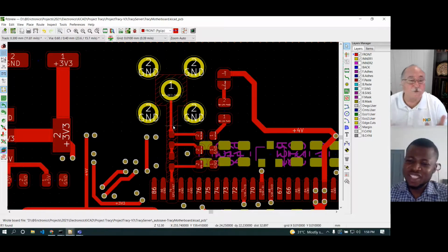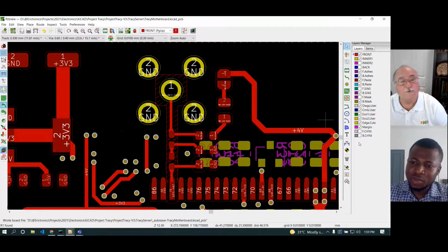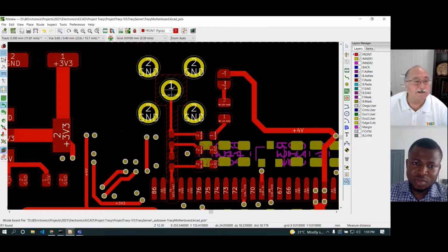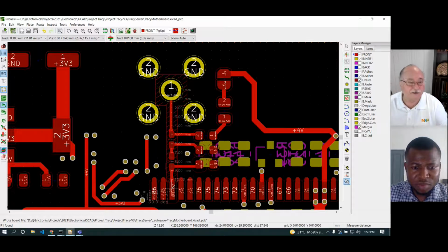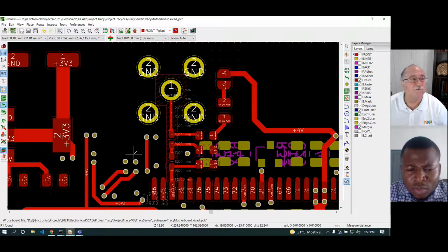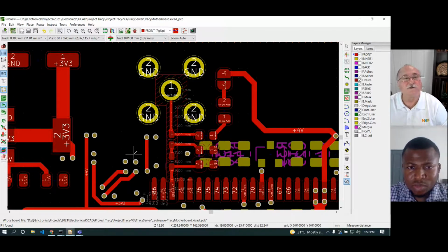So the important thing here is, in order to couple the maximum amount of energy from the antenna into the receiver and from the transmitter into the antenna, to make sure that you keep those impedances matched as closely as possible, because that gives you the maximum amount of energy driving through there, because the little reflections do reduce the power that's going out there. I mean, in the case of a structure this small, you probably can't even measure it.